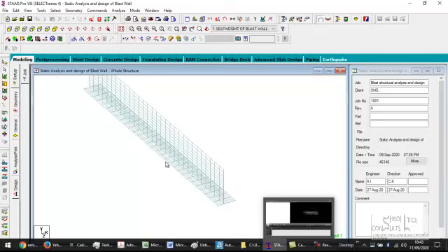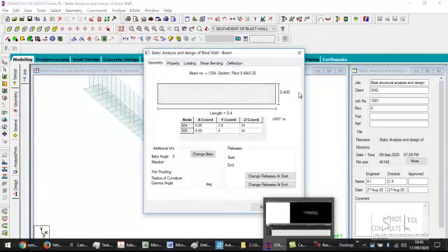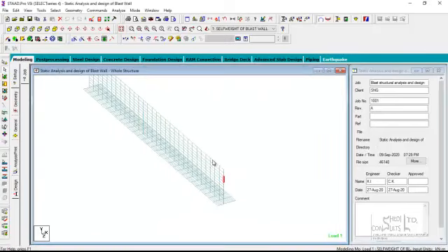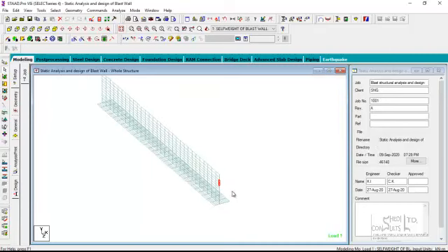We talked about the cross-section of the columns between the blast wall. We said it is 300 by 400, as you can see. Now the 400 is in this direction, so as to gain the direction where it has its maximum moment of inertia.